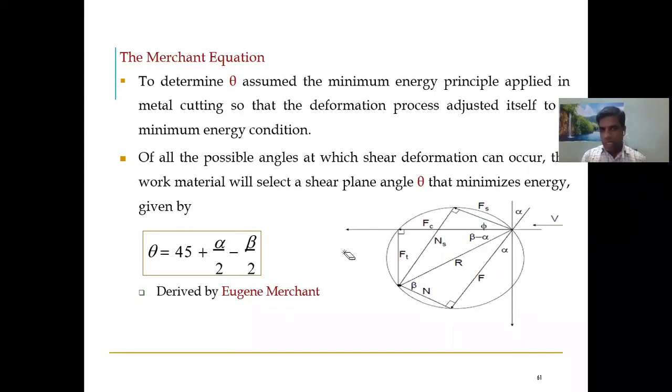That's why this formula is called the Merchant equation, and this circle was also given by him. That's why it is called the Merchant force circle, or in some books, the Merchant circle. Please remember, this is one of the important questions that may come: what is the Merchant circle? If it is a 2 mark question, you can just write something about the resolution of forces falling within the circle, that is called the Merchant circle. But if it is a 5 mark question, you need to explain and draw the diagram. If it's a 10 mark question, you need to explain, draw the diagram, explain the angles also, and even mention the Merchant equation.